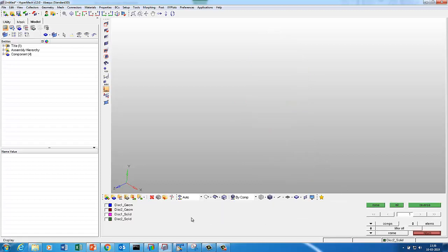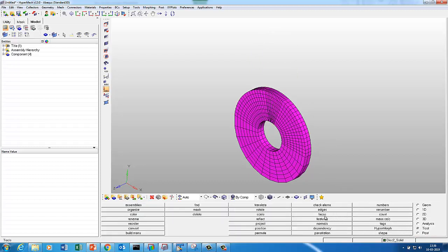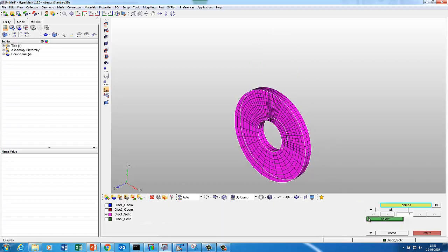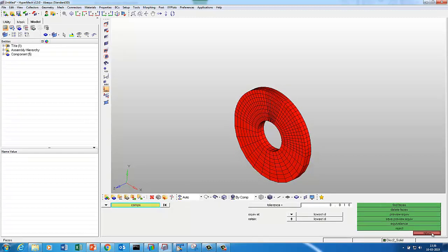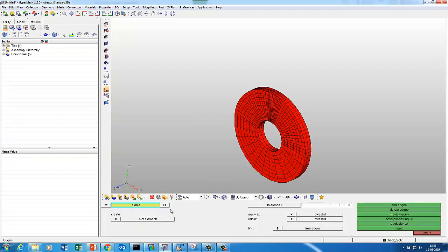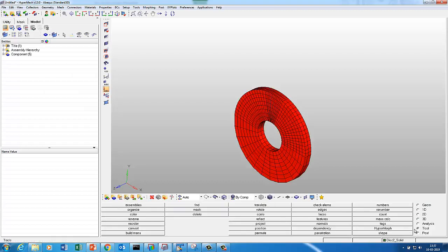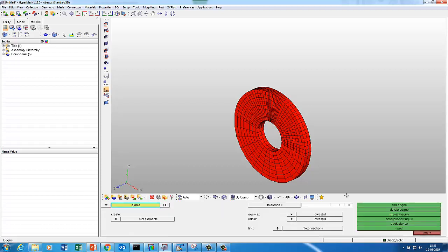Now we'll check the solid element connectivity. How to check the solid element connectivity? Go to tool, go to faces and just check the faces. Get faces. So once you've done that, you just select the face and do Shift F3 and find whether you get any free edge. So no edge found, selected element. They are enclosed volume. This is one indication, and the second is also check a T connection. No T connection, that means your solid elements have connectivity.